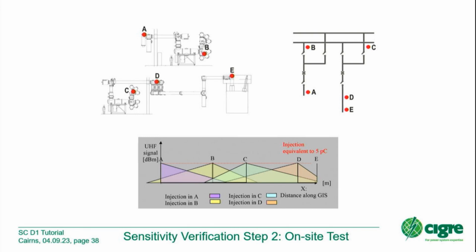Now I would like to say for standard GIS, the UHF technology as it is, starting at roughly 200 megahertz, that's fine and okay. Of course, maybe there are some cases where we can improve, but from that point of view, I would recommend doing a one-to-one test with another insulating rod in the test setup at the manufacturer site, for example, to check what the PD magnitude of that kind of defect really is and what the measurement result is with a proper PD measurement system.